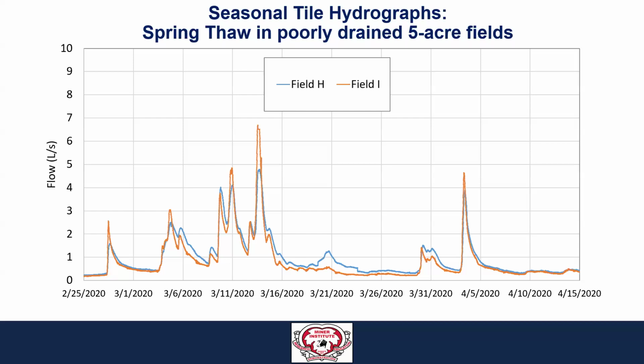So again, that's reflective of the challenge of working with our drainage entering into a lake where phosphorus is the limiting nutrient. Even with small impacts from agriculture, where we may be retaining 98-99% of that phosphorus, that small 0.5 pound, 1 pound per acre contribution can still have a significant impact on our water resources.